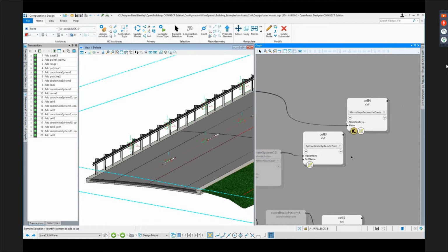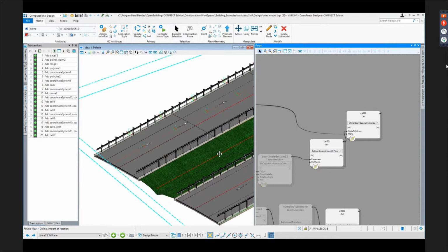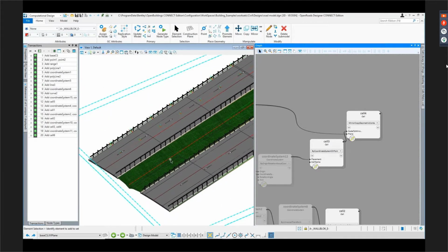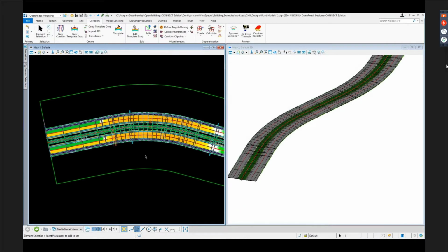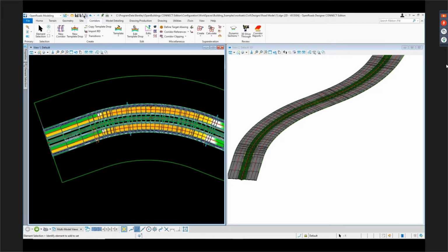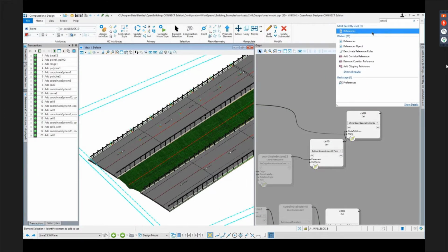But this methodology gives you a reusable script, in order for you to lay them out by just running the script, or updating the script anytime there's a change in your model. Like for instance, in this video here, once the main corridor changes, I just drag the alignment drastically in order for you to see what will happen.